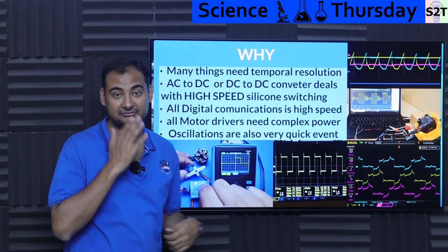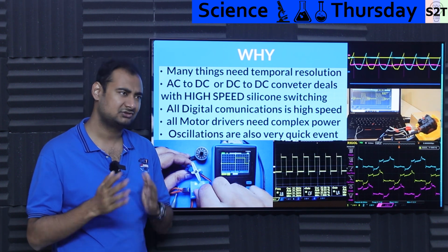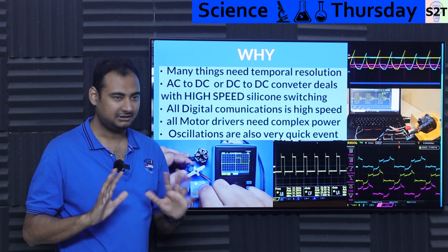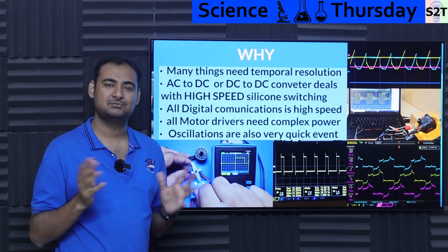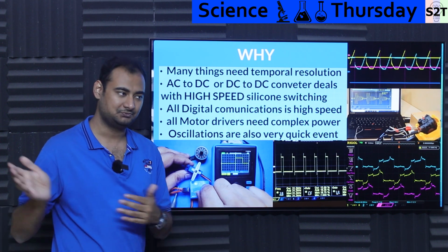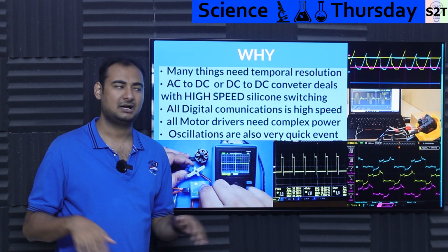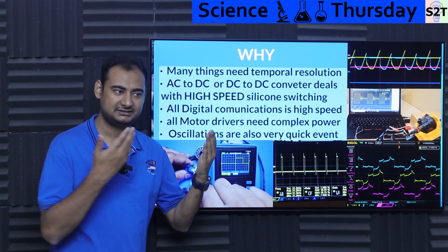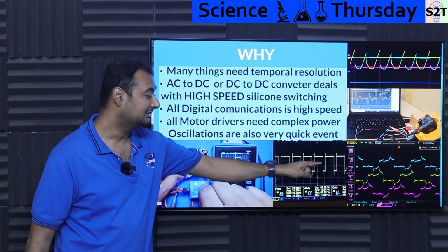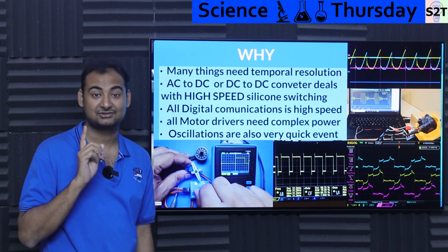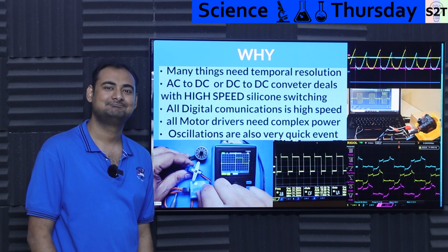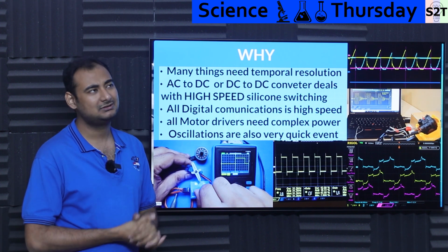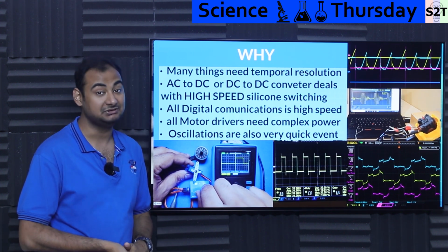For example, the waveform of a BLDC motor is generally almost like a three-phase, but if you noticed your Ender 3 stepper motors, they work, everything is fine, but they are noisy. And there is this magic board known as the silent board. You put it in and everything is quiet. How the heck did that happen? Same hardware, same load, how the heck did it become silent? If you see the waveforms side by side on an oscilloscope, you'll be like, I see it now. That's why you need this temporal resolution for the modern world. In the old world, yeah, you can get by without it, but in the modern world, you need it.